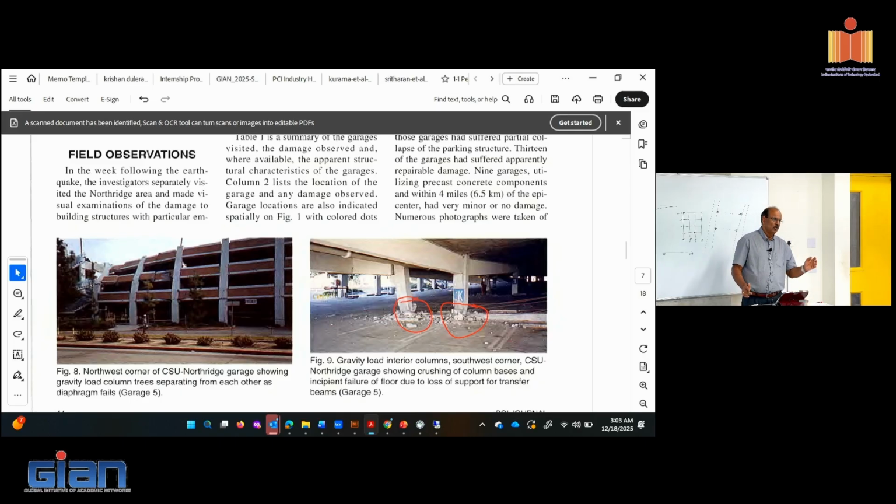And if they don't move, in fact, in one of the Northridge buildings, when they didn't move, then you lose members because the seat that they provided is not large enough. So they lose the floor. If the perimeter frame was designed well, it will take the load. That's exactly what happened in the Northridge event. Typically, with precast, even for our gravity load system, only the beam connections are made shear connections. Columns are all monolithic. Oh, I see.